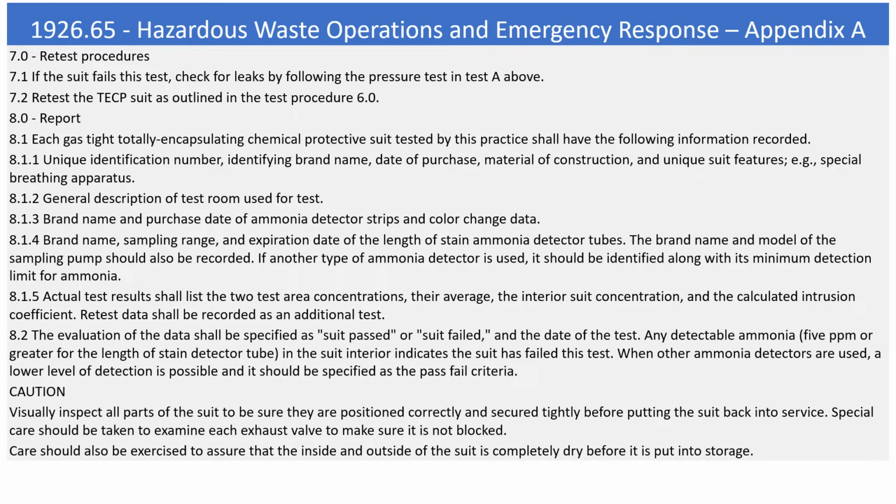When other ammonia detectors are used, a lower level of detection is possible and it should be specified as the pass-fail criteria. Caution: visually inspect all parts of the suit to be sure they are positioned correctly and secured tightly before putting the suit back into service. Special care should be taken to examine each exhaust valve to make sure it is not blocked. Care should also be exercised to assure that the inside and outside of the suit is completely dry before it is put into storage.